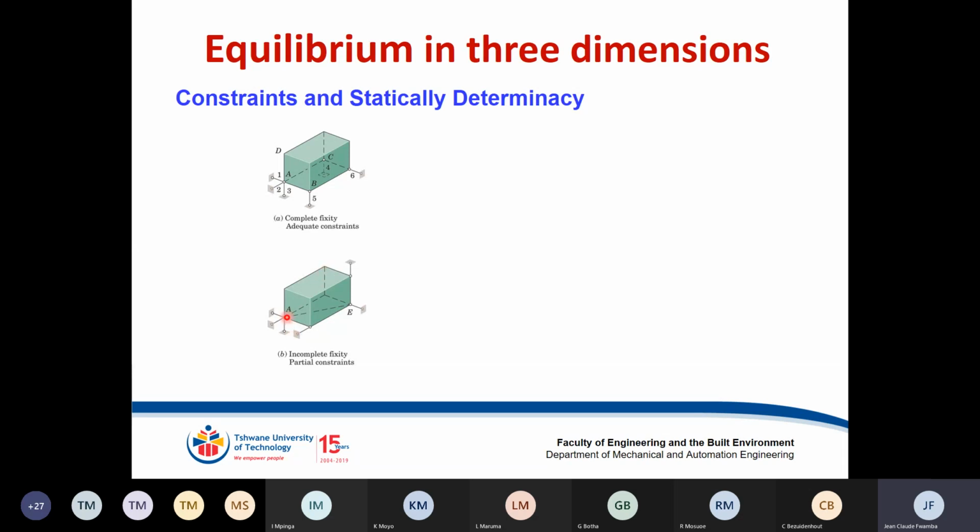If you check around that point line there, my block can swerve sidewise, meaning there might be a possibility of motion on the Z-axis. Let's check on the Y-axis. I've got 2 restrictions, which will be sufficient. X-axis, I have these 2 as well, which would be sufficient, I believe. So the only issue is on the Z-axis.